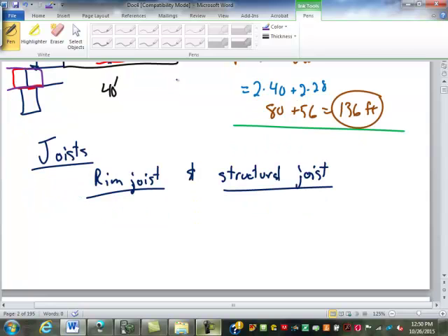So let's go over that, just for the heck of it. L over 480. Let's just assume there might be some tiled floors in here, so we're going to design it as strong as we possibly can, as strictly as we possibly can. So what is the 480? Well, the length of these is 14 foot, right? Nope. 480 is just a divisor constant.